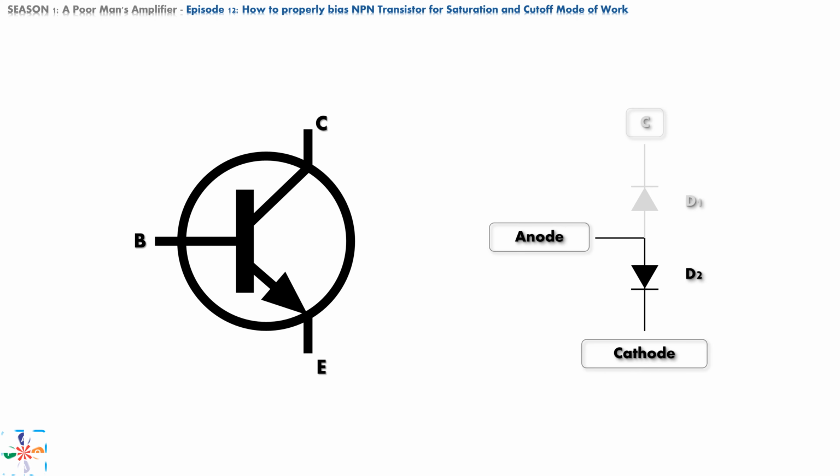Since we are not interested in collector-emitter junction, we have grayed it out, as it is not important for this discussion. Again, we must point out, that in real life, two diodes in series like this, do not form NPN transistor. This equivalency is just a simplified explanation of internal voltage drop of base emitter junction in BJT NPN transistors.